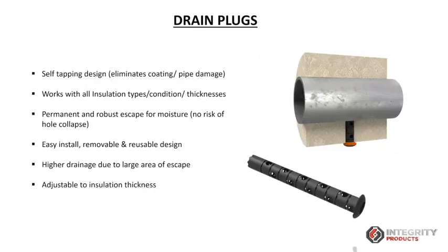What we are offering, the integrity drain plug, contains a self-tapping design. That means we don't need any power drill for that. It can sit on the pipe. We can see that there are certain sharp edges, but these are made from polyphenylene sulfide, this drain plug, so it's not going to scratch the pipe. Once we install it without any mechanized or power drill, it's not going to touch the pipe. It's not going to scratch any coating on that.